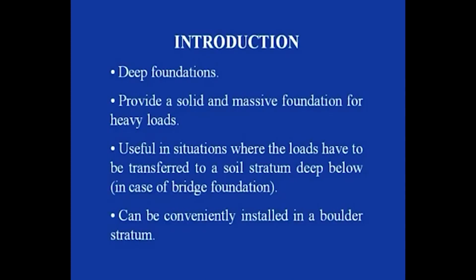We all know that when the loads from the superstructure are quite high and the soil bearing stratum doesn't have sufficient bearing, then we need to go for deep foundation. So well foundation is one of that type of deep foundation. It provides a solid and massive foundation for very heavy loads.